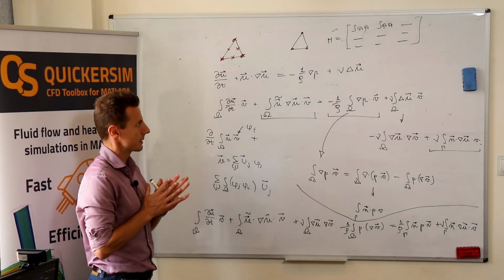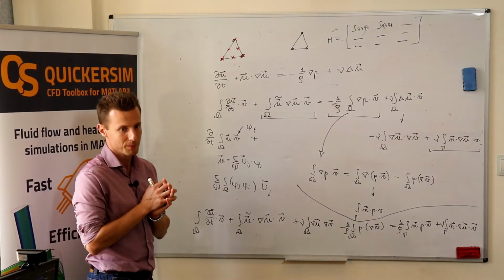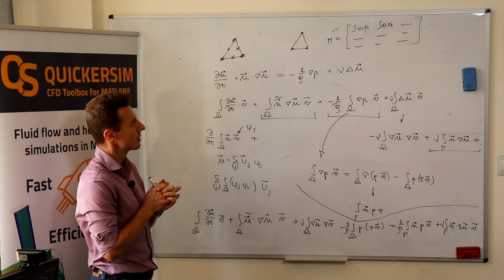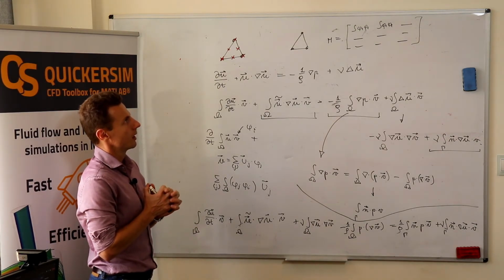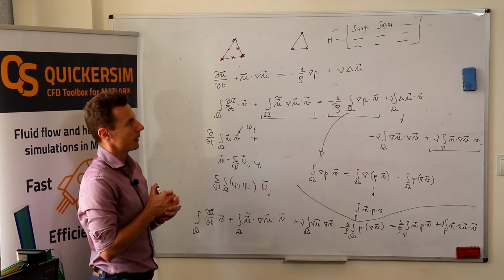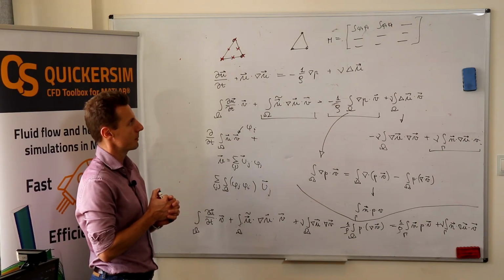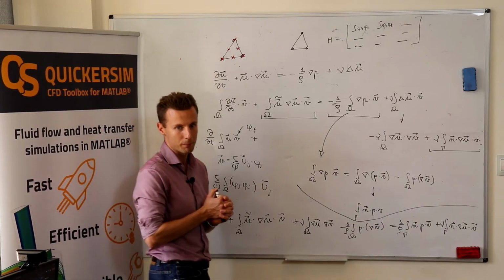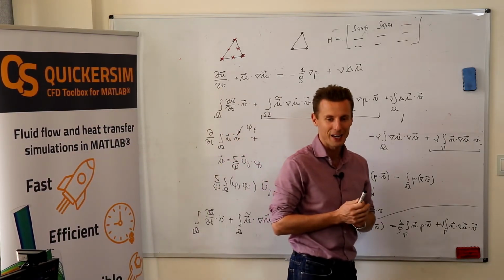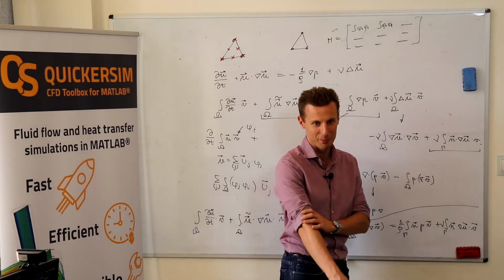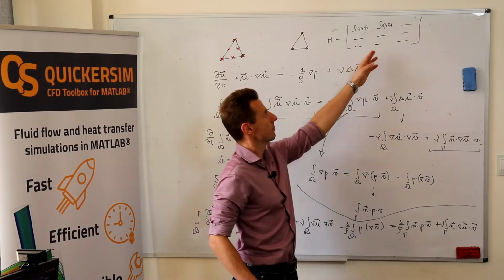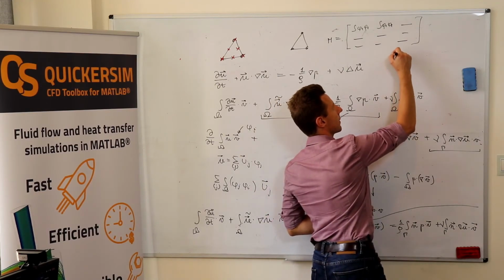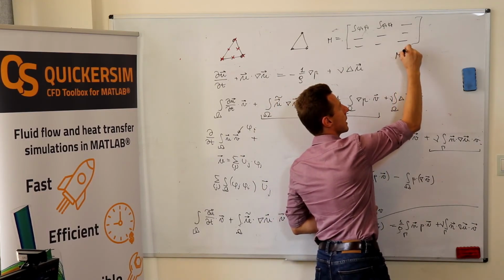So it's always implicit. But people in finite elements do something that sometimes helps with the stability, or sometimes helps with the computational cost of solving the problem. They attempt doing what you asked about. Something that is done is matrix lumping.